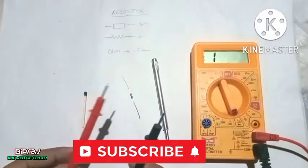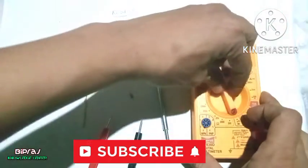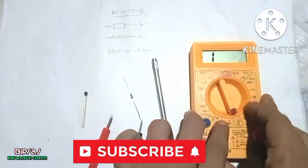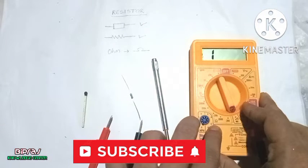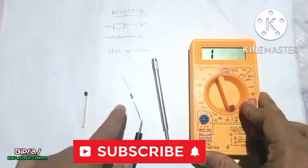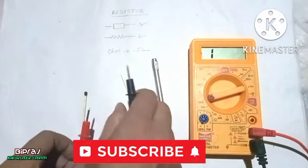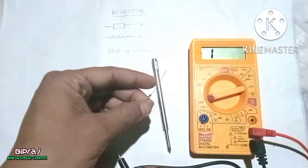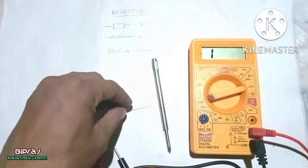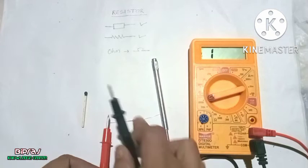Let's check it through our multimeter. For that we have to set our multimeter into resistance mode, and suppose we don't know its value, so we can set it at the maximum range and check its value. It is non-polar, so you can place the positive or negative probe on either end.